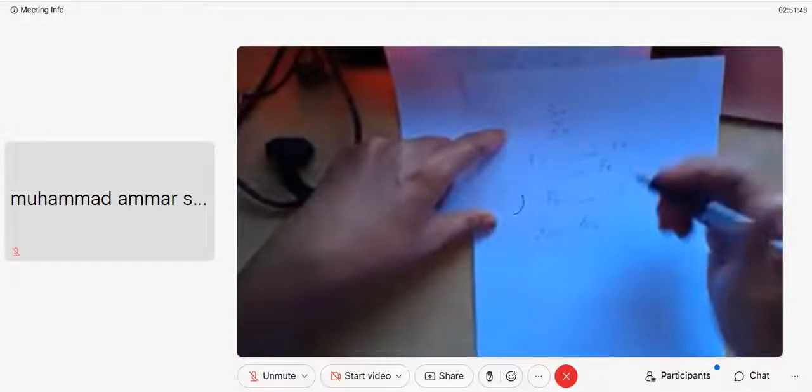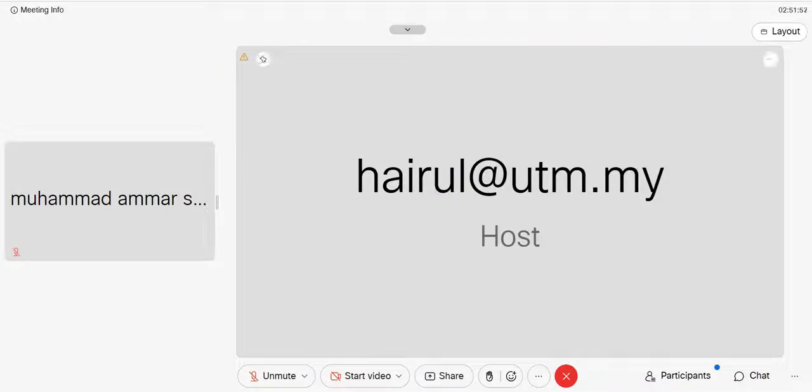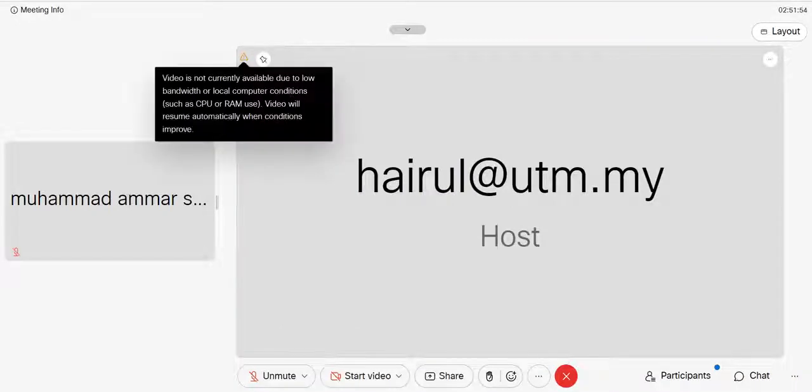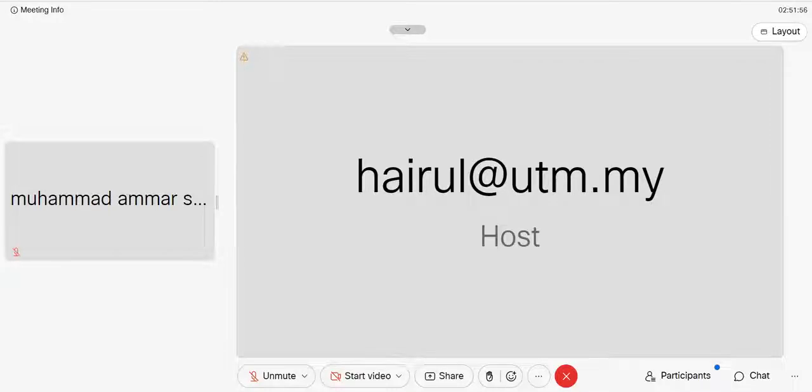When you get your Ft, so what is power? Remember, power is Ft times velocity over 33,000 in English units. Remember, it is the tangential force on your pinion times V over 33,000. So you will get your horsepower.